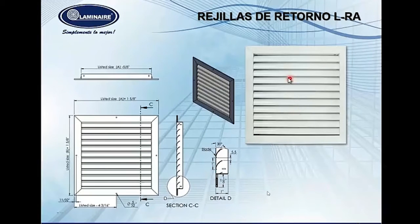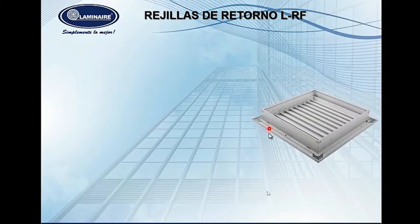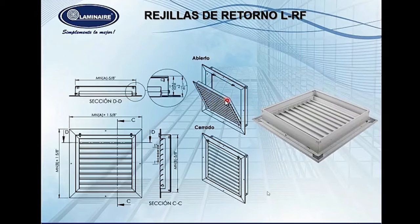The LRA grid has these characteristics. These flaps are totally fixed to the frame. Here we can see the profiles. It is a flap like an air blade that permits the air, when it is passing, not to cause inner turbulence. These are the LRF grids. They have a central panel that is removable, which can be opened and closed depending on the conditions of maintenance in a specific application, and a filter could also be installed inside the grid.